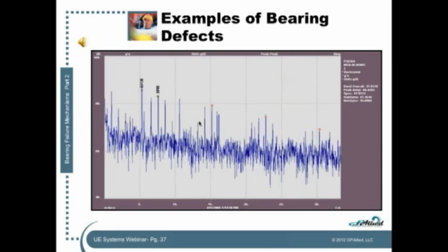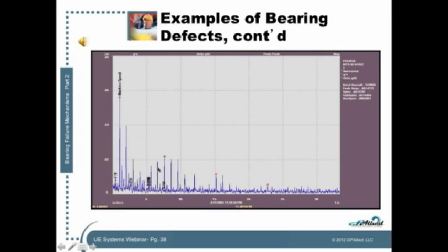But we were able to pick it up in zone 1, so it's a little bit later in zone 1. And we know that from the fact that not only is the ultrasonic signal loud, but it also has a pattern starting to develop. So if we go to zone 2, now we're into regular vibration data. We can see the non-synchronous peaks here in the spectrum, but the amplitudes are really low.